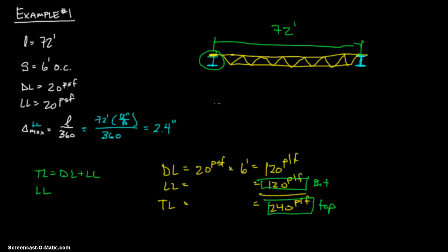That might be a poor assumption, but you can call your fabricator and see what each one costs, and then go ahead and use the one that is cheaper. So in this case, I would use a 36LH09. And you could also go ahead and look at your live load max deflection and calculate, and you'll find that that's correct. It fits that.